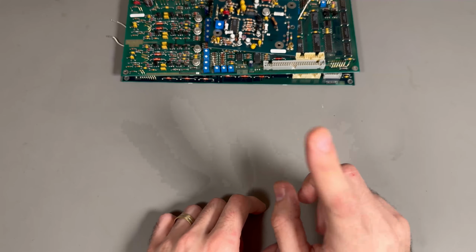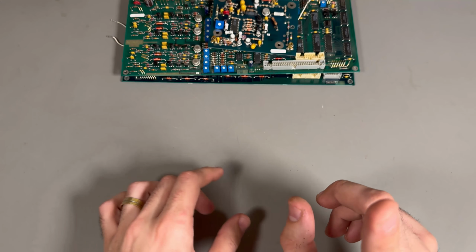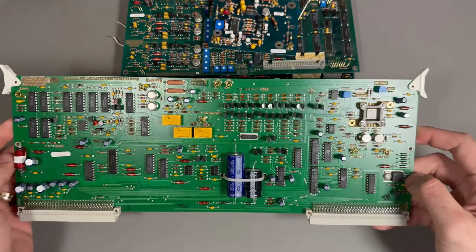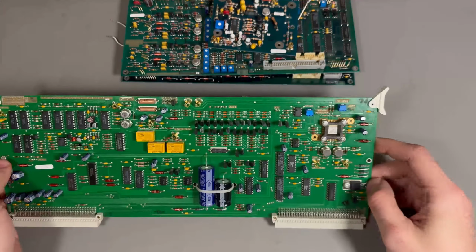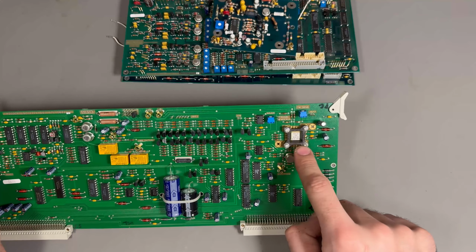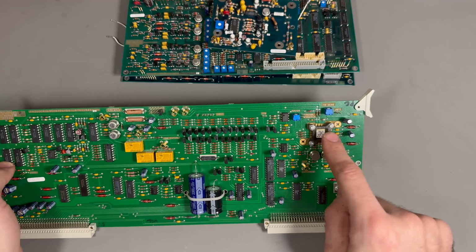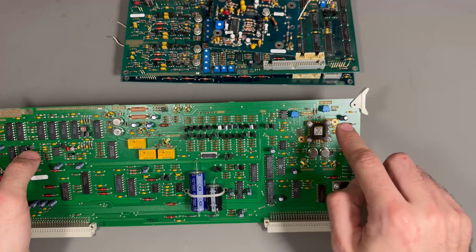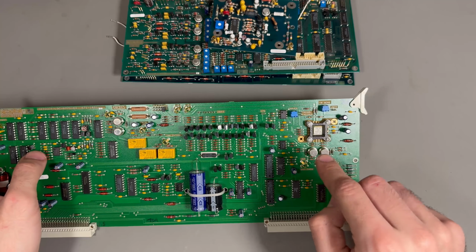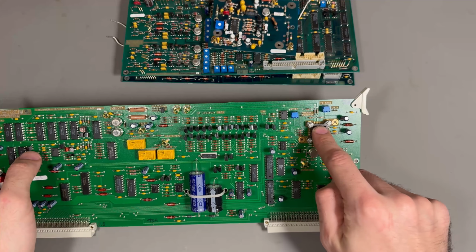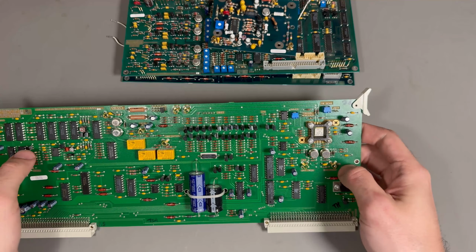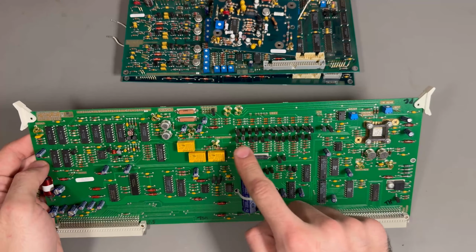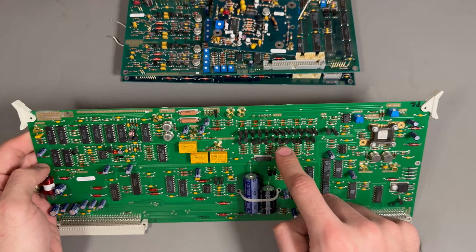And we're now gonna get into first the trigger board, which is this. The trigger board, insane construction. So A6, Tektronix A6, these are HyperCon, and HyperCon refers to hybrid PCB connections. So you take off these 4 screws, and there's a very fine interface between the package of the ASIC and the PCB substrate. Very, very good for high frequency response. A bunch of transistors which I have no idea what they do.